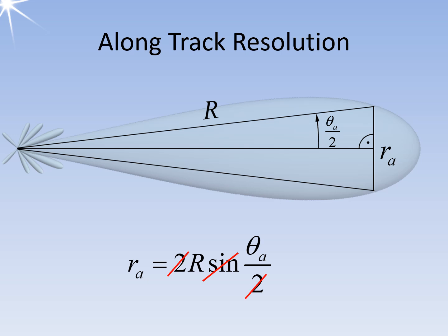After that, the two 2's cancel each other out. However, the value of the angle must now be entered as a radian. 0.3 degrees corresponds approximately to 0.005 radian. At the ground, these 0.3 degrees at a distance of 10 kilometers result in a minimally resolvable range difference of 50 meters. The same radar in a satellite would result in a resolution of 5 kilometers at a distance of 1,000 kilometers, which is out of the question for practical use.